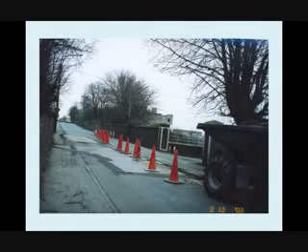Going back to one of the other specifications, again, there's quite a few things wrong with this, but concentrating on the cones there, which have no reflective sleeve. TS4, the Department of the Environment document we listed earlier, as well as EN 13422, the European standard, clearly state that a certain percentage of the conical section of each cone should be retro-reflective. And they need to have the correct retro-reflective sleeve on them as well. 750mm cones have a different cone sleeve to 1 metre cones, so again, they need re-sleeving correctly. Naked cones, as I like to call them, shouldn't be on the site at all.